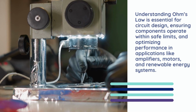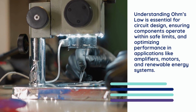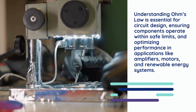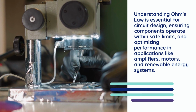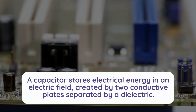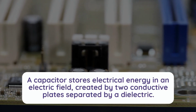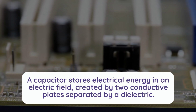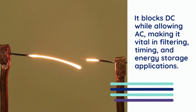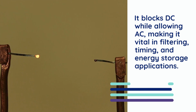Understanding Ohm's law is essential for circuit design, ensuring components operate within safe limits, and optimizing performance in applications like amplifiers, motors, and renewable energy systems. 3. What is the function of a capacitor in a circuit? A capacitor stores electrical energy in an electric field, created by two conductive plates separated by a dielectric. It blocks DC while allowing AC, making it vital in filtering, timing, and energy storage applications.